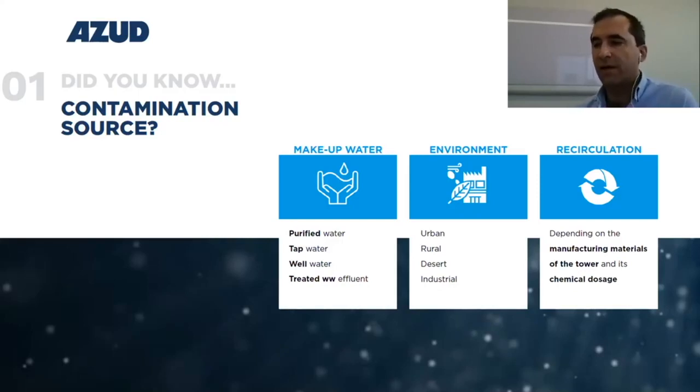Also, the installation itself can be a contamination source, as pipe degradation by high and constant chemical usage will release suspended particles to the circuit. So all these particles can eventually decant and affect the water flow and therefore the heat transfer of the cooling system.